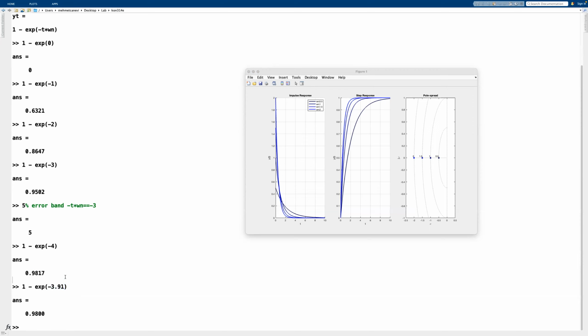Those are more about the second order system, and you can use those formulas with zeta equals 1 for the first order system. Since there's no overshoot, we don't have any overshoot formula for this because it is directly equal to 0 for a first order system. So it's important to know that the system's model is an easy one, and we can just use the exponential term here in order to analyze it and acquire the settling time.